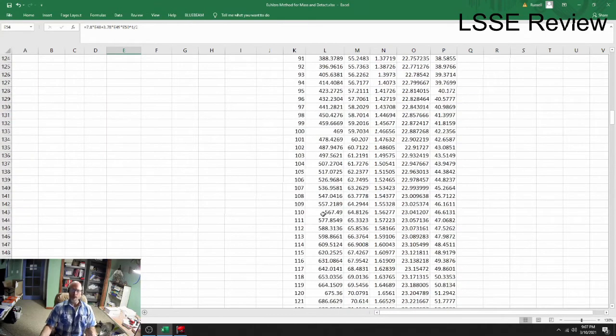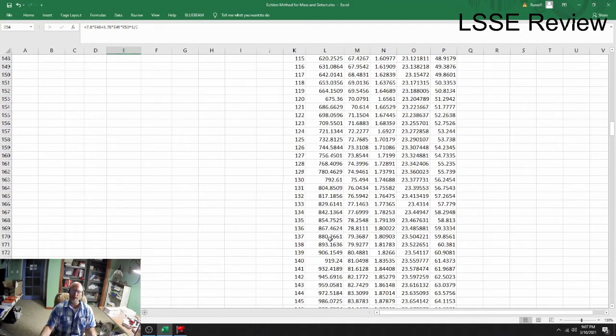If I come down here and find out when 725, we already know it's under 124 seconds. But depending on the variables, height of the ceiling, things like that, my detector temperature is only 53 degrees Celsius. Well, if I'm using like a 165 degree Fahrenheit heat detector or sprinkler head, which correlates to about 74 degrees Celsius, well, I haven't even gone off yet in terms of where I'm at, in terms of the fire.